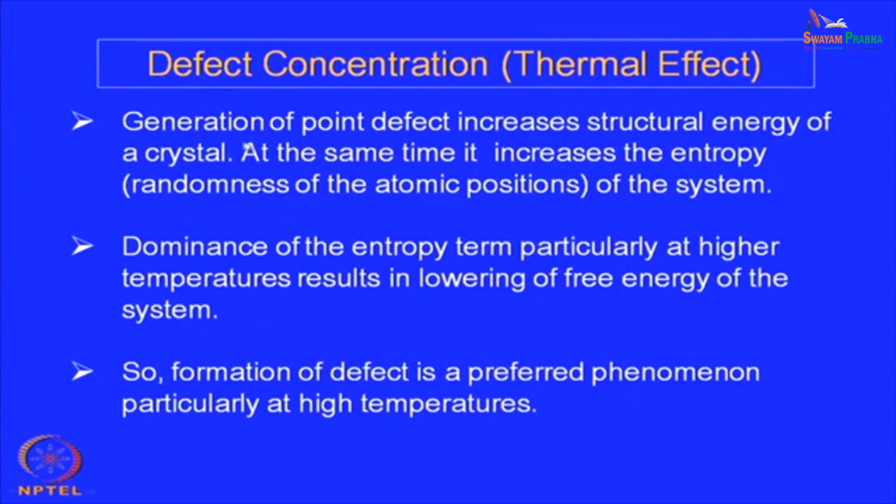The generation of point defects increases the structural energy of a crystal, and at the same time it increases the entropy, the randomness of the atomic positions of the system. Dominance of the entropy term, particularly at higher temperature, results in lowering of the free energy of the system. So, formation of defects is a preferred phenomenon, particularly at high temperature.